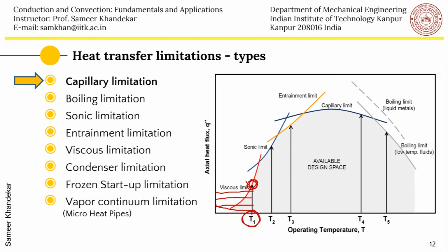So basically what you do is you increase the evaporator power by a certain amount, let's say 5 watts or 10 watts. The temperatures will rise. You will bring them down to the operating temperature which you want by cooling down the temperature of the condenser. The condenser is also usually over-designed so that you are not limited by the capacity of the condenser, which itself can be a limitation sometimes. But we are assuming that is not there in this particular case.